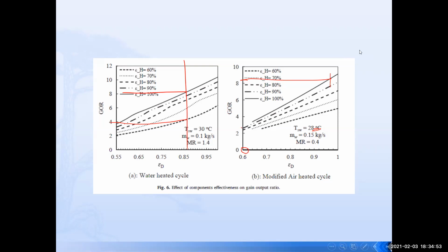The ones that we have done in the lab with a packed material have an effectiveness of about 0.6 for the humidifier, whereas the latest humidifier that we have built was a 3-stage bubble column humidifier, and we could reach an effectiveness of 0.92. So more than 90% effectiveness, while for the packed bed humidifier, it was about 0.7 or so.